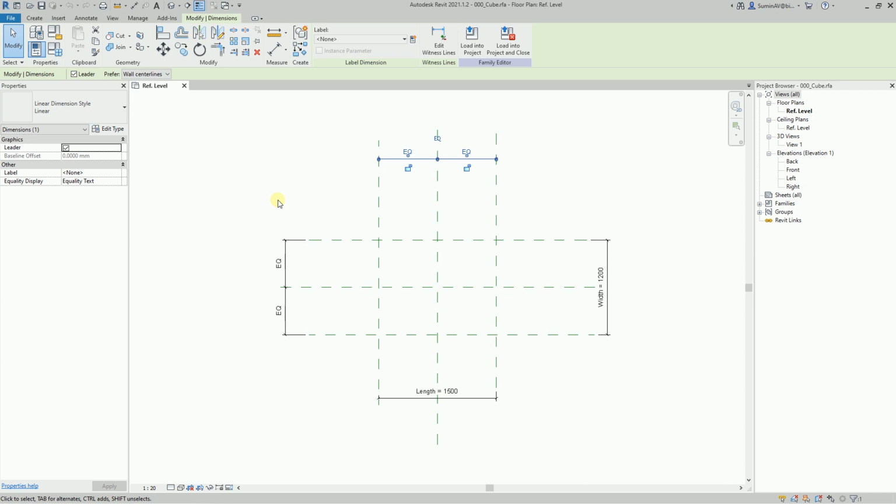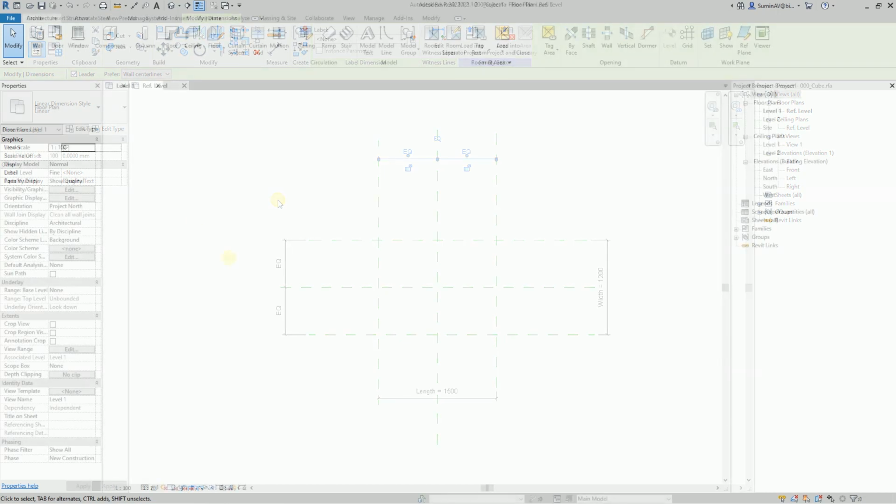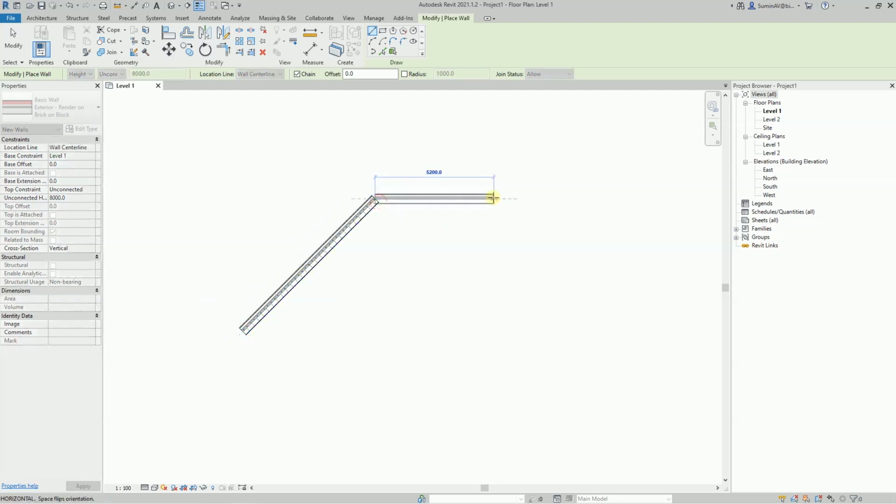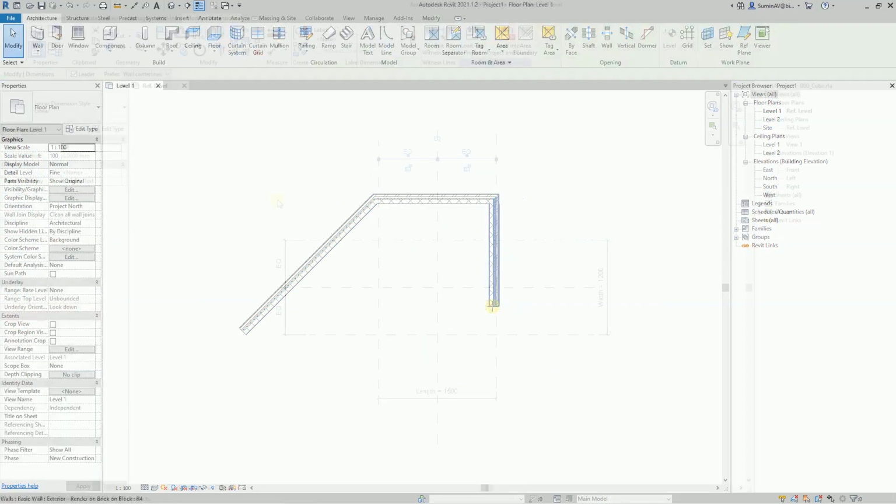Now that we know it, let's proceed to modeling. Revit supports 3 object modeling techniques. The first technique is line-based object modeling. We create a line and shape geometry along this line. It's in this way that we create reference planes or walls. In the same way, we create sections of pipelines, air ducts, or cable trays.